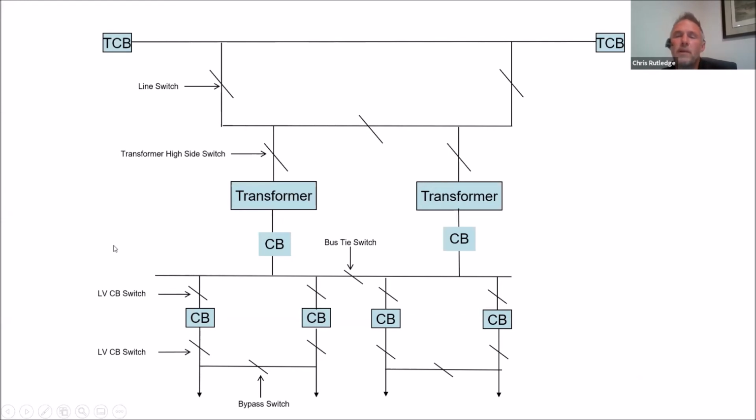So this was the point of setting a capture on your phase current. With any event that happens, and it could be out here on a line somewhere, everything in series with that particular breaker is going to see that through fault. Let's just say that we have a 3-cycle breaker out here on this line. And I feel like this is where a lot of our transformer damage comes from, and utilities aren't aware it's happening because of the way they're doing their testing.